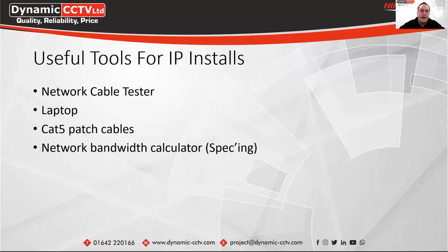And something that we do always recommend to installers is to have a laptop, an engineering laptop, in case there are any issues, such as doing password resets through the SADP tool, remotely configuring devices, accessing the web front ends. The best tool that you can have is a laptop with an Ethernet connection, where you can actually connect to the network and be able to scan the network using SADP.